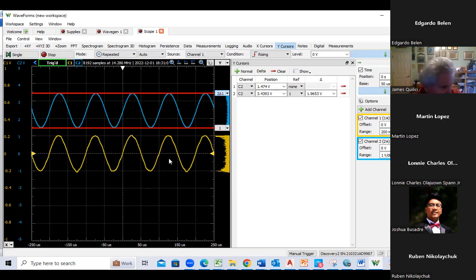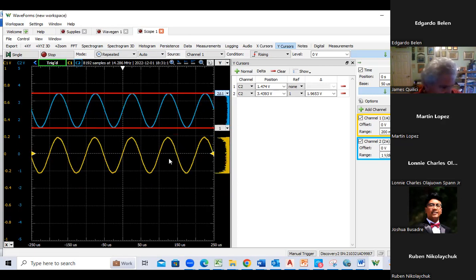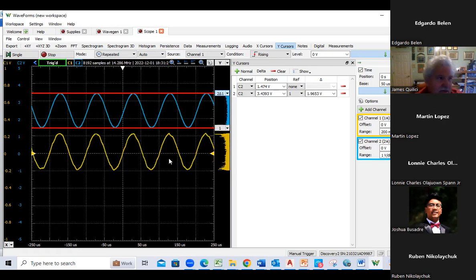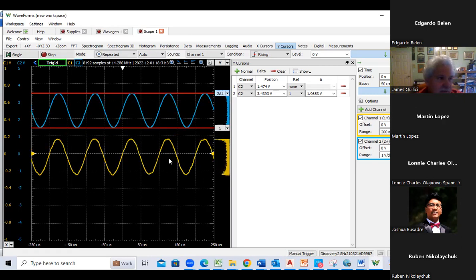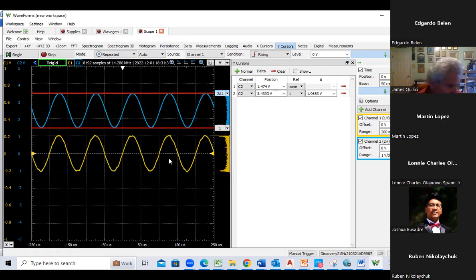Okay, so what we want to do in step 11 is find the, so step 9, basically run it at 10 kilohertz. You did your simulations last week, and I recall that in the AC sweep the high pass dominant pole was the emitter capacitor, and its 3 dB point was in the 400 to 500 hertz range. So if you're running at 10 kilohertz, you know you're going to be in the passband.